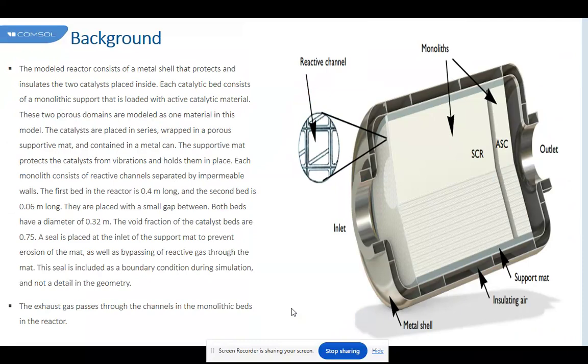The outlet cone was replaced by a straight pipe of the same diameter as the monolith and 30 millimeters long, which has a marginal effect upwind of the domain and makes it easier to register the radial profiles of the variables of interest at the outlet of the substrate.